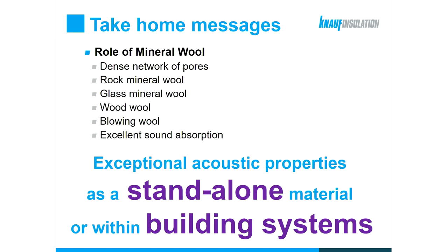And here are the messages of this part of the webinar related to the role of the mineral wool. Earlier, we saw the microstructure of the mineral wool and the dense network of pores, which is actually responsible for the acoustic performance. Furthermore, we mentioned several types of the mineral wool: the rock mineral wool, glass mineral wool, wood wool and the blowing wool. And we said that there is no best product or the best technology for all the purposes.